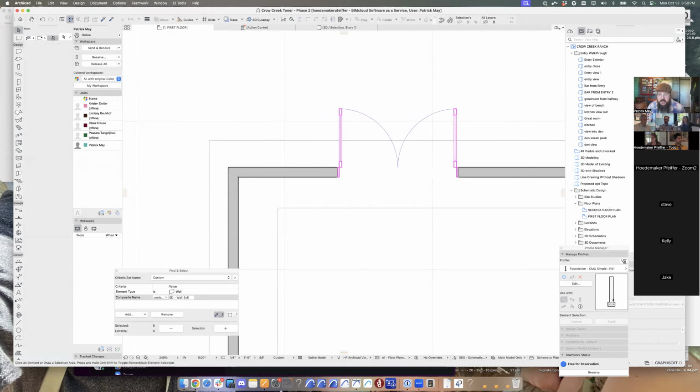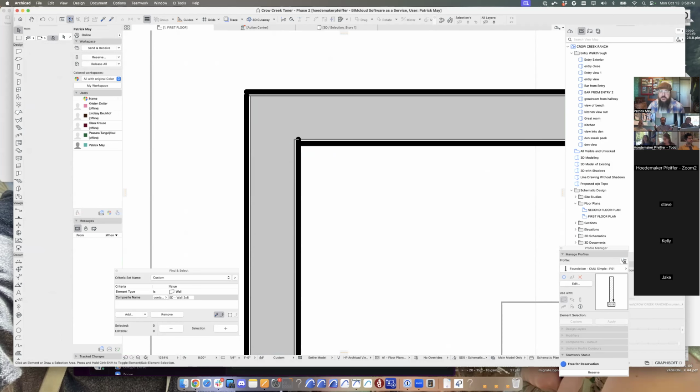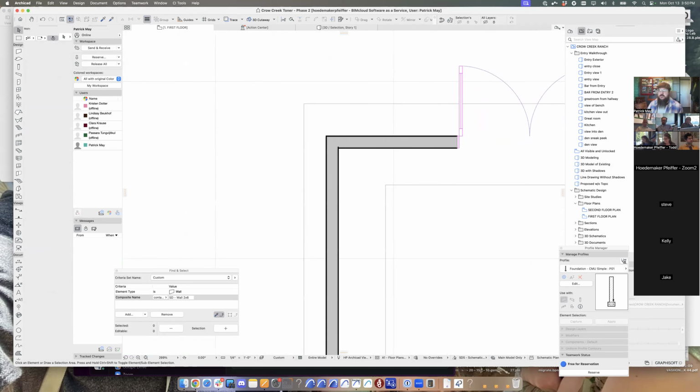The other thing that I wanted to review was the graphic overrides. So where the composite says this is how this stuff shows up, the pens show how thick those pen weights are. The building materials show how these fills are. All of those are default settings for how things appear in ArchiCAD. The graphic overrides are the exceptions. This is how I want things to show in these other instances.